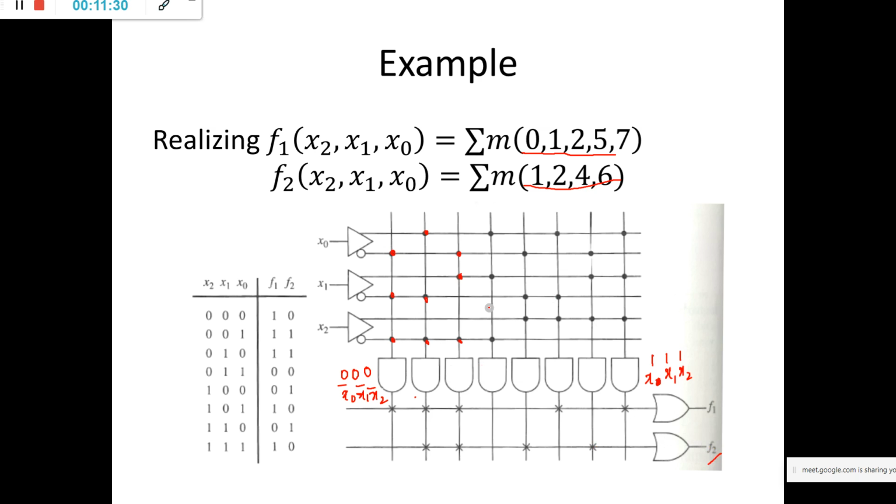using PROM. So in PROM what we will do is, as you know, the AND array is fixed and the OR array is programmable. The AND array is nothing but a decoder. It will generate specific canonical terms. Wherever the function F1 is having 0, 1, 2, 5, 7, there you put a cross mark indicating a connection is done.